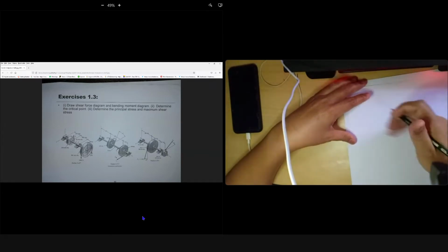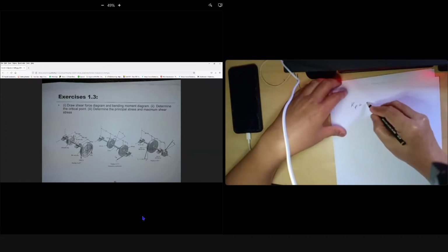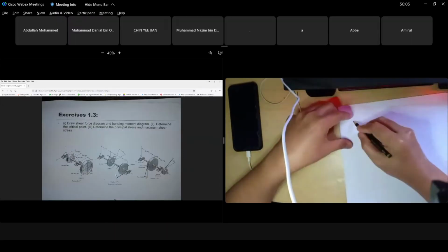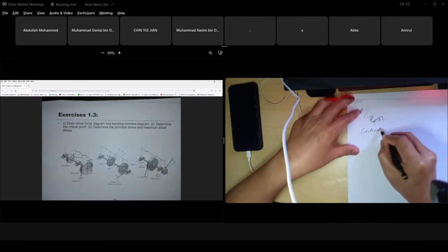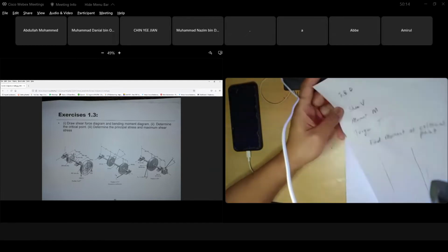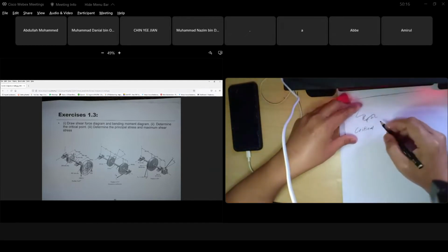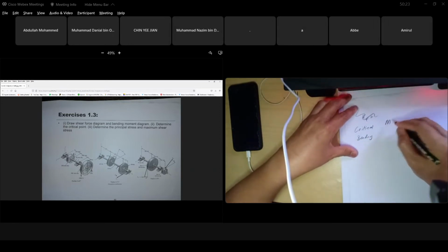Then what will you do? Be careful about KF. Remember our fatigue stress concentration factor? Be careful, we have bending. At the critical point, don't do everything. Which one is critical? At the shoulder, maybe. Then we go for bending, and you have your total moment.